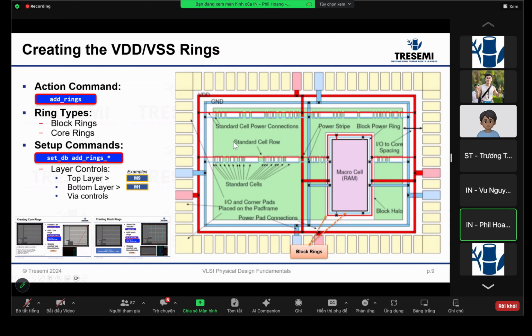Usually the routing inside the chip uses the regular metals, and the lowest, metal 1, is usually a thin metal. A lot of routing from metal 2 to metal 6, metal 8, whatever, are what we call regular metals. Then at the higher level you have thicker ones, called thick metal, and then ultra thick metal, and the RDL redistribution layer.